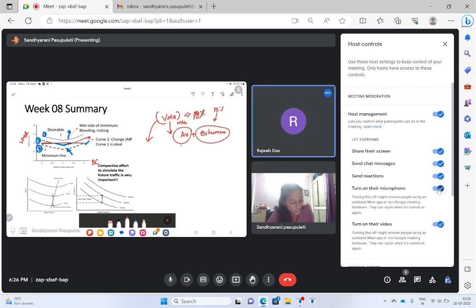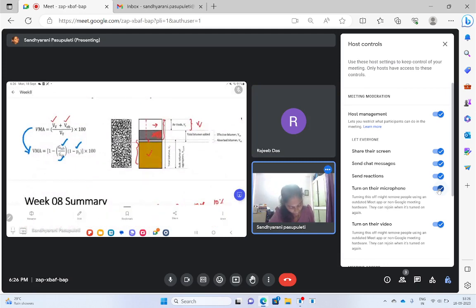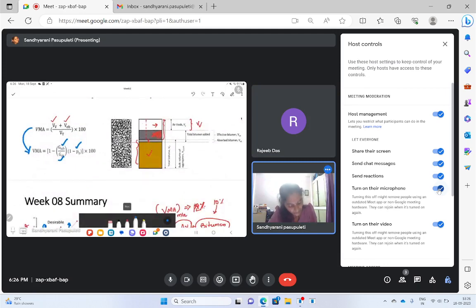So, in order to have minimum... Madam, VMA is only the part of the bitumen that is absorbed by the aggregate. That is the VMA, na? No, VMA is actually, if I can show this phase diagram. So if you come here, sir, this is VMA, the top 4. VMA means bitumen plus air voids. Effective bitumen plus air voids. So this always should have some minimum amount of space available so that we can...